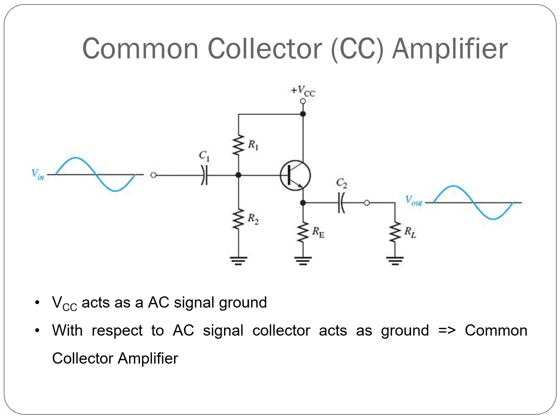A key takeaway is that the collector remains at a steady voltage, making it a fixed reference for signal variations at the emitter, and the output follows the input. Same shape, nearly the same voltage, but with strong current drive. So this is what makes the common collector amplifier a great buffer. It provides signal integrity, no inversion, low output impedance. It makes it perfect for driving loads without signal loss.